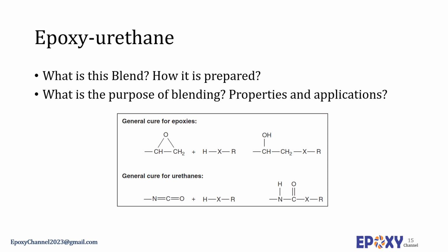Some epoxy urethane hybrids in one and two component structural adhesives have had success in the automotive industry, where high impact resistance, fatigue resistance, and high bond strength to a variety of substrates are valued characteristics. Blocked isocyanate prepolymers have been mixed with epoxy resins and cured with amines as well. These blocked prepolymers will initially react with the amines to form amine-terminated prepolymers that cross-link with epoxy resins. Urethane amines are also offered commercially for use with epoxy resins to develop hybrid adhesive systems.